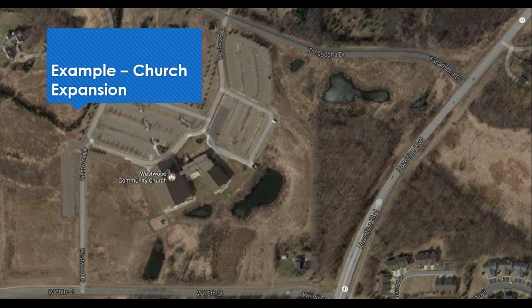And then we got into SimTraffic. At the time we weren't using vStro and vSim, and I'm not sure that we would go to vSim for this. SimTraffic is a little bit easier to use, but we ran all these 15-minute scenarios with the church. You get really peak events of people coming and going, and we ran SimTraffic to see how far the backups would be. Coming out of this, there was the physical infrastructure out here. There were shoulders out here so they could kind of use it as a bypass lane.